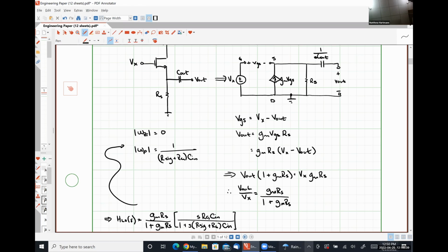All right, how did you guys feel about the low frequency analysis? This is fairly straightforward, nothing particularly wild or crazy. Yes, sir. Why is there no voltage drop over the capacitor? Can current flow through this capacitor? Through this impedance? No, because it's open circuit. So if there's no current flowing through it, there's no voltage drop over it, thanks to Ohm's law. So Vout is this voltage. Circuits 1 stuff. As always, that's what I'm going to tie stuff back to, because that's how my brain works from teaching that class so many times.